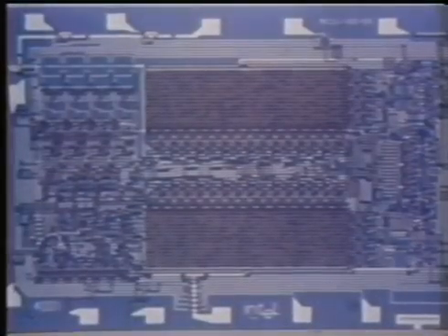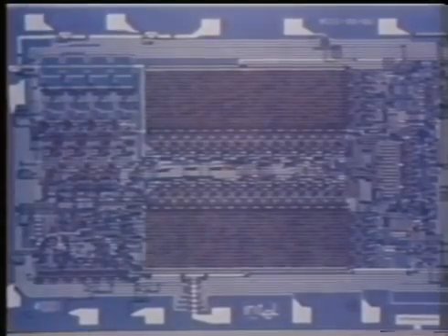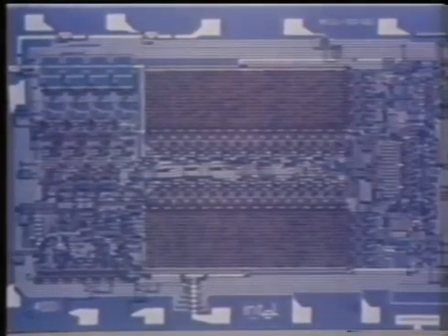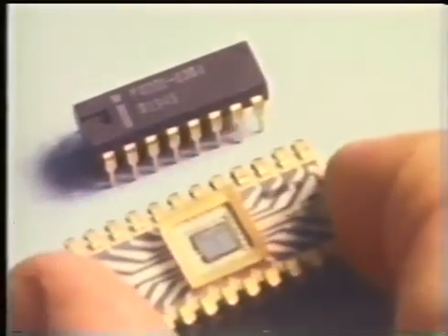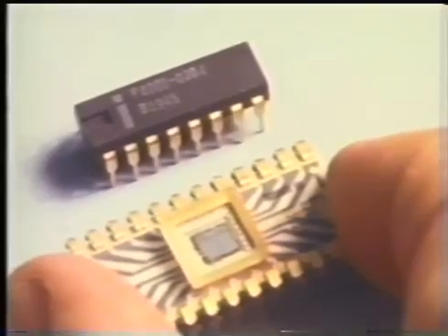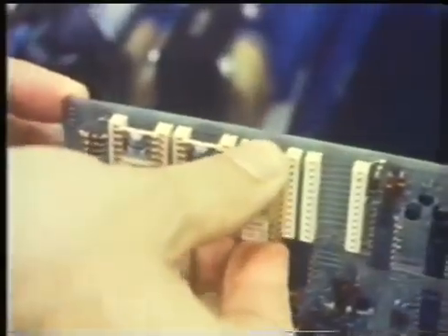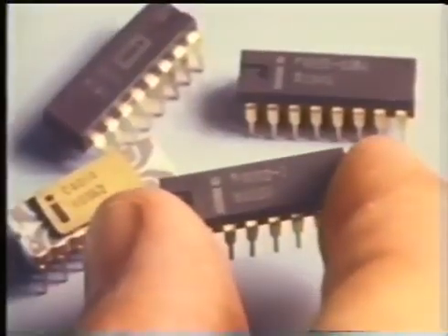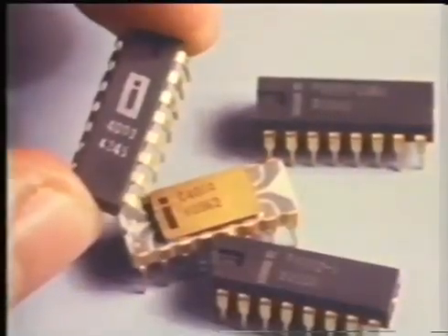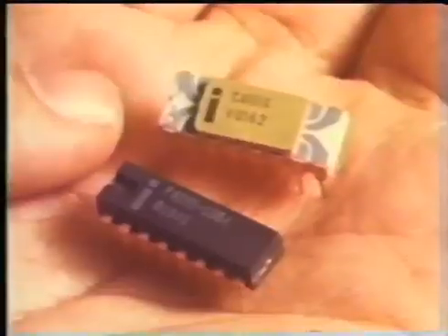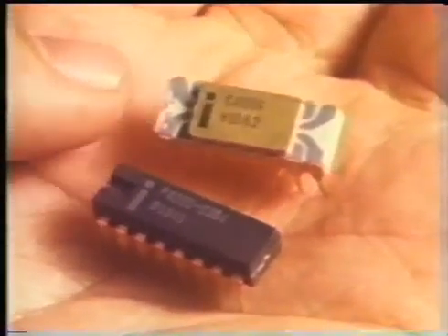The 4001 ROM acts as the personality of the system and holds your microprograms by means of a customized metal mask. To make prototyping easy and inexpensive, you can simulate the operation of this 4001 with our 1701 field programmable and erasable PROMs. The 4002 RAM reads and writes data, and the 4003 shift register is used for I/O expansion. The smallest computer you can build costs less than $50 and is composed of 1 CPU and 1 ROM.